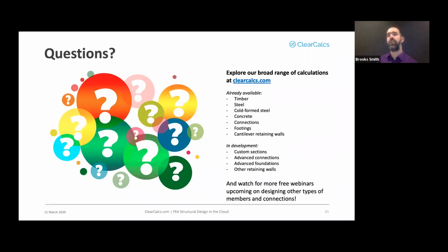One note: AS1684.2 does provide information on specifying the laminations. Thank you very much for that. That does partially answer a question I incompletely answered first. Yes, that is still current, and you can use AS1684.2 here. If that defines how frequent your fasteners need to be and what type of fasteners you use, you can refer to AS1684.2.